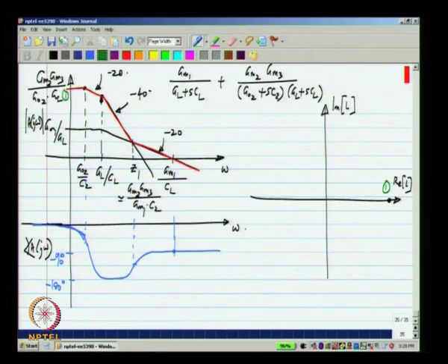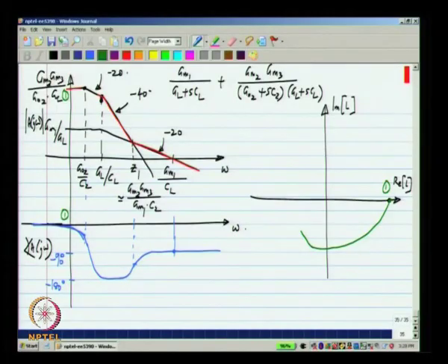It starts on the positive real axis, and as you go further, the magnitude keeps on lowering, but the phase becomes more negative, there will be more and more phase lag. So, this plot spirals inward in some way. Finally, it goes all the way down to 180 degrees, and remember, the phase shift due to 2 poles will asymptotically reach 180 degrees, it will not be exactly 180 degrees ever.